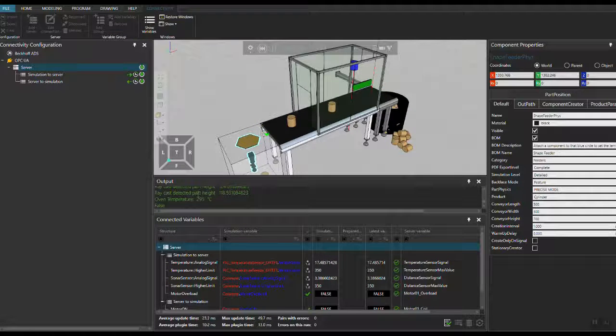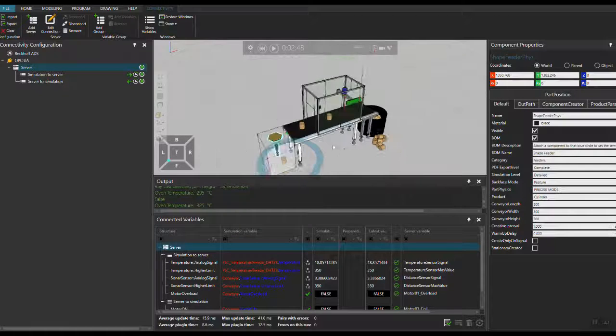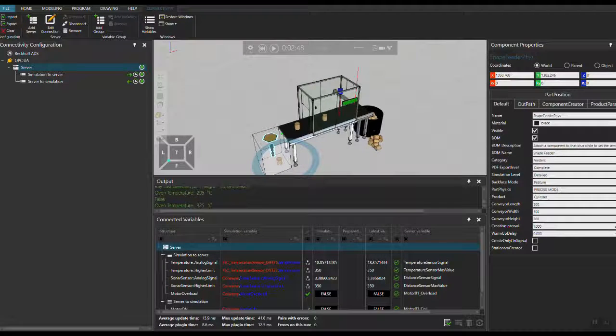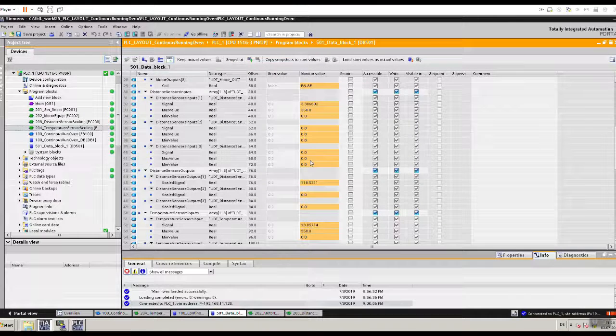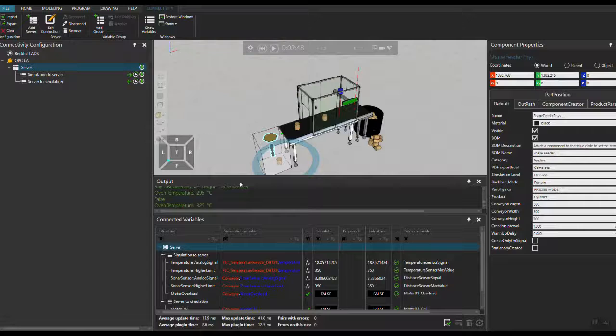Yeah. So you can see we got an oven temperature of 295, and as soon as it went below this set limit of 325, it stopped. Now the only way to start this line is that the operator should go to the machine and fix the issue so that the temperature can go up again. Let's assume the operator has fixed the issue, and now we can see the temperature is back over 320. Yeah, so our simulation is running. In this case, it's again changed to 331.